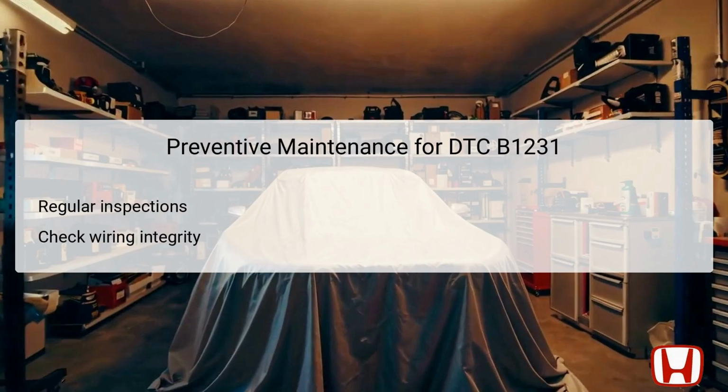To prevent future occurrences of DTC B1231, regular maintenance and inspections of the HVAC system are essential. This includes periodic checks of the wiring connected to the evaporator temperature sensor to ensure there is no sign of damage, corrosion, or loose connections that could lead to an open circuit. Furthermore, cleaning and maintaining the climate control system helps ensure that airflow is unobstructed and all components are functioning as intended. Implementing a proactive maintenance schedule, including routine diagnostics and testing, can catch underlying issues before they escalate into significant